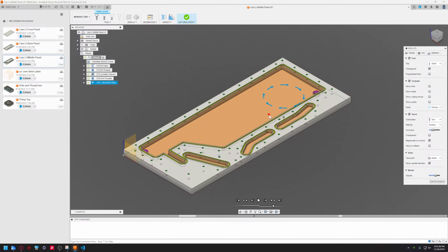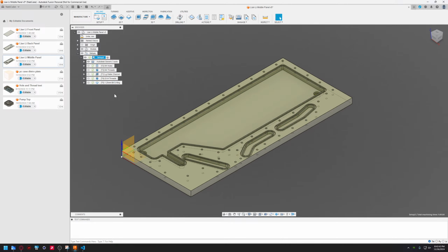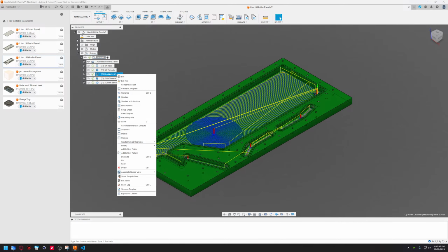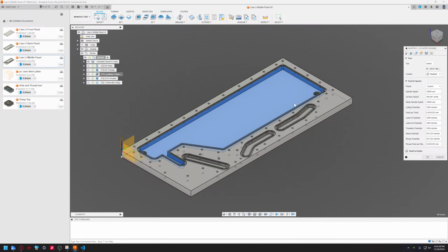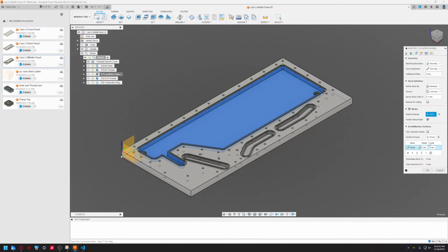This one I'm going to actually try it this way to see how the finish is. If the finish ends up being to where I have to stop the machine or something, I can always go back in and add a finish pass by just telling it for the large water channel to leave stock. I can leave so much radial or axial stock to leave, because it's gouging out so much at a time. 1 millimeter on either side.